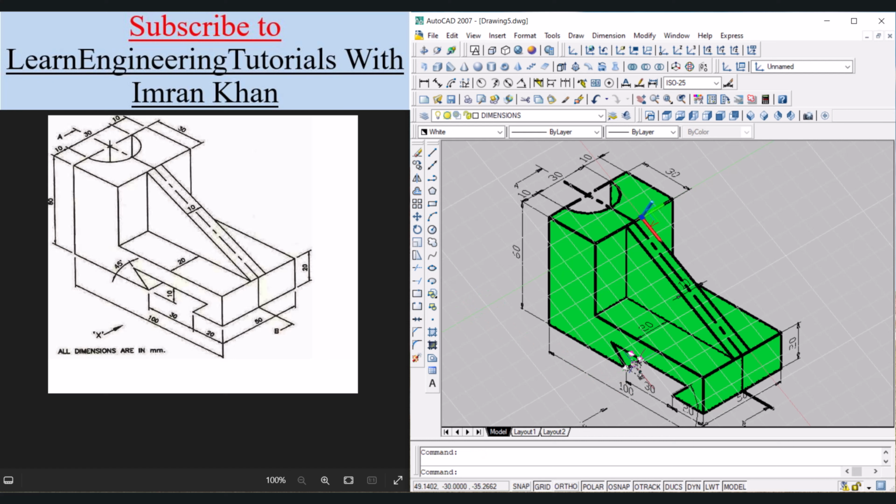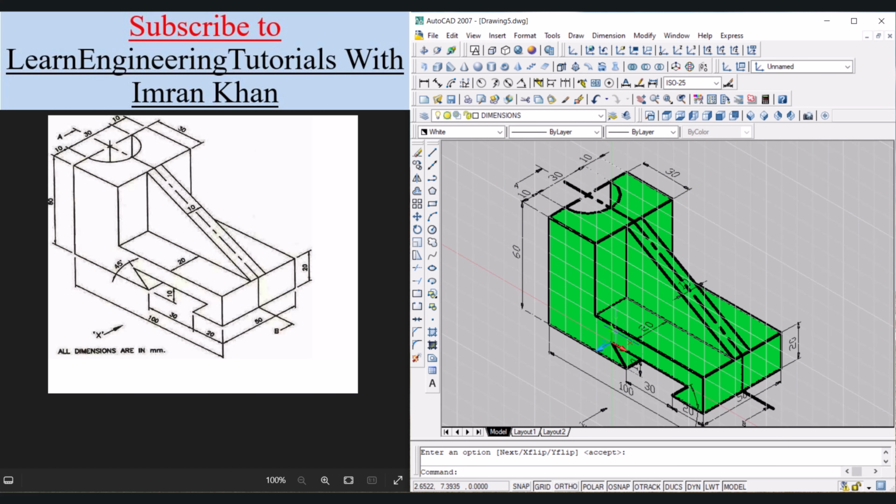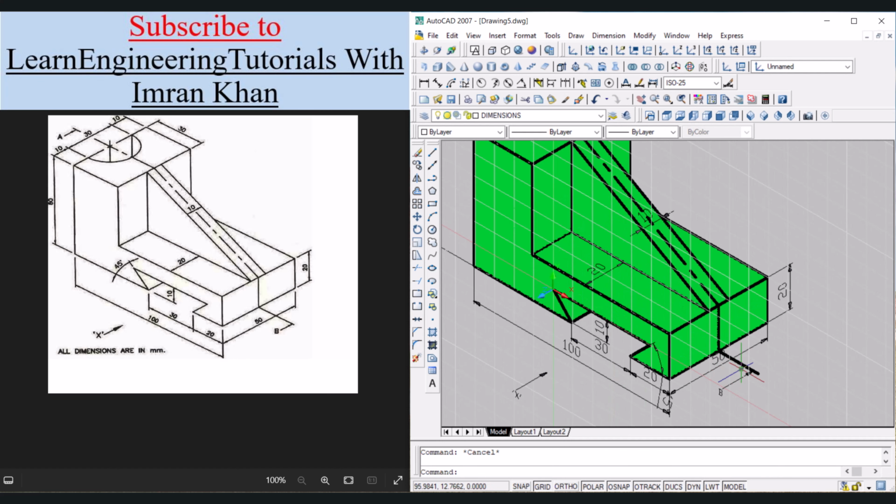We will move this 10 value a little bit over to this side. So for that we have to select the face UCS, click over to this face, click accept, and now we can move this 10 value. Click and move it a little bit over to this side. Press escape. So now the object is complete.